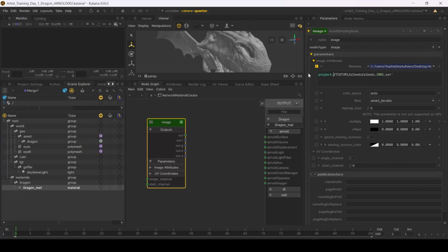code snippets. I will just type it and open my string. And I will replace this with the UDIM. I'm going to open the bracket, the UDIM. So it's going to call all my UV tiles in. So I don't have to type 1001, 1002, 1003. I can bring them all at the same time. And then I will go at the end and I will press control enter to run this code.